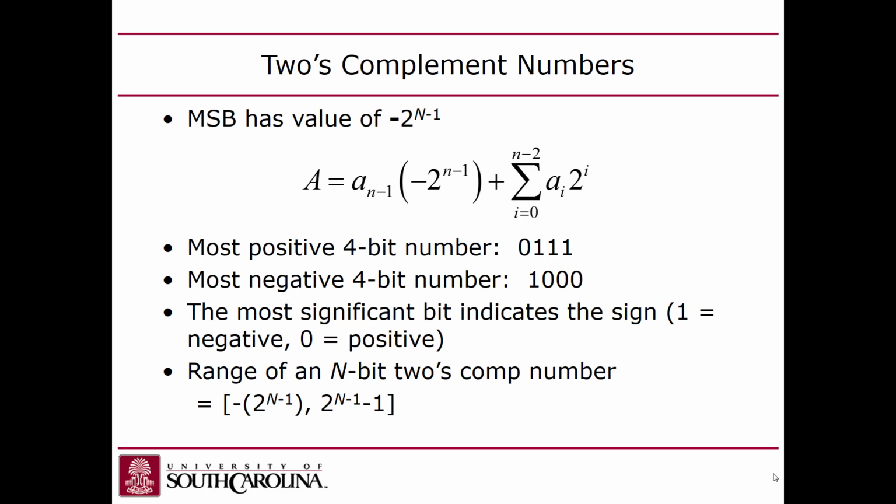If you've got unsigned numbers, if you have two unsigned numbers and you add them, you're not expecting an overflow, right? So if you add two unsigned 4-bit numbers and you get anything greater than 15 as the result, 1, 1, 1, 1, then you're going to have an overflow, and that would mean something's wrong, right? Assuming you're adding. It's different if you subtract two unsigned numbers. But if you add two unsigned numbers, the carryout would mean overflow. If you're adding two signed numbers and you get a carryout, as we did here and in the last example, it's not as meaningful.